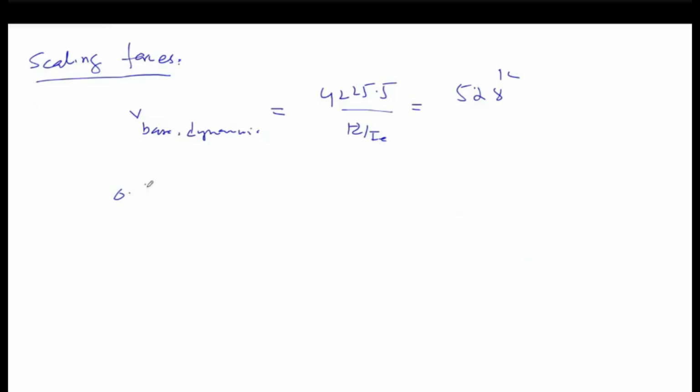Now taking the 0.85 base shear obtained through the static procedure, the ELF. So we know that the base shear was 737. So taking the 85% of this will give us 627 kip. Now the V dynamic is still less than the 627 kip. So we can see that this will govern now. Okay. Our dynamic base shear should be equal to 627 at least.